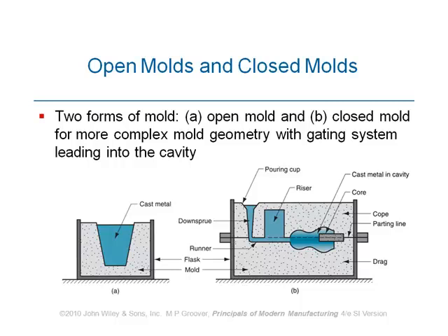That one, this cavity. What is it doing? It's been designed in a way that this riser solidifies after the solidification of the cavity is complete. Meaning that during the solidification process, if there are some void spaces produced inside the part, we have got molten material available here, and this molten material will be sucked into the cavity to fill it in.